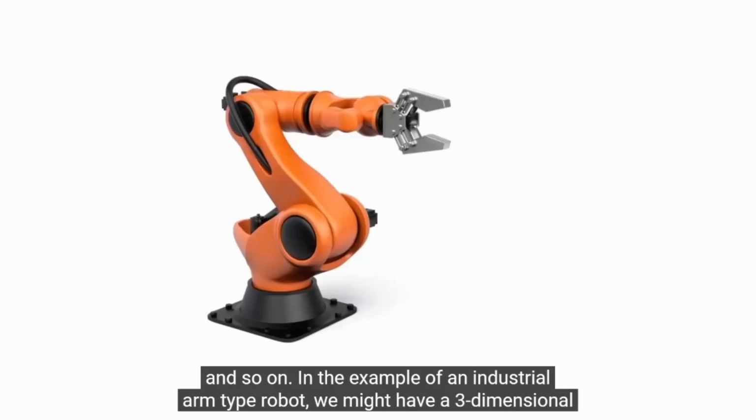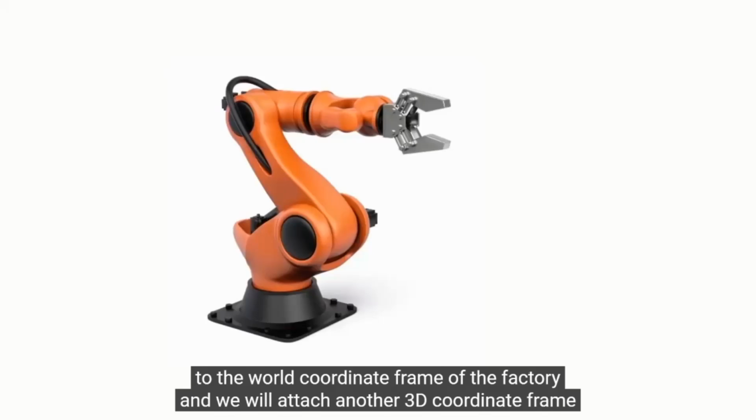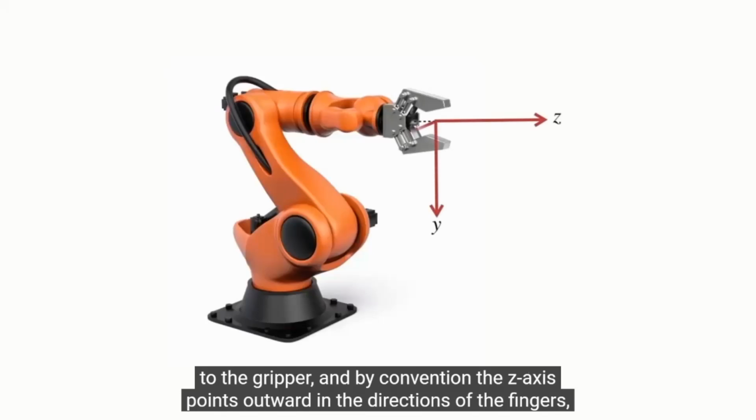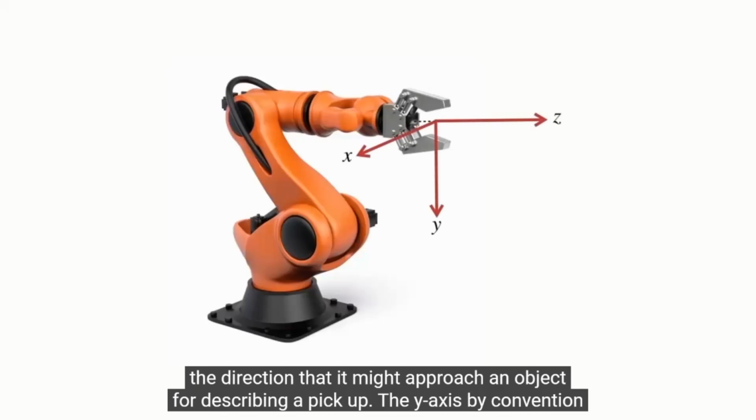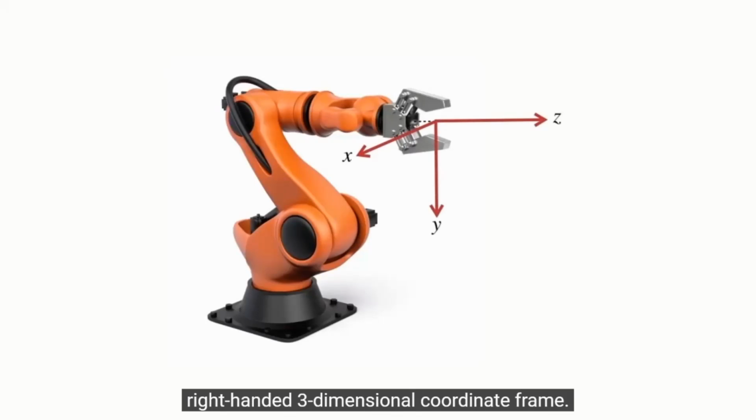In the example of an industrial arm type robot, we might have a three-dimensional coordinate frame attached to the base of the robot to indicate where it is with respect to the world coordinate frame of the factory, and we will attach another 3D coordinate frame to the gripper. By convention the z-axis points outward in the direction of the fingers, the direction that it might approach an object that it's going to pick up. The y-axis by convention is the direction between the fingertips, and we draw in the x-axis so as to create a proper right-handed three-dimensional coordinate frame.